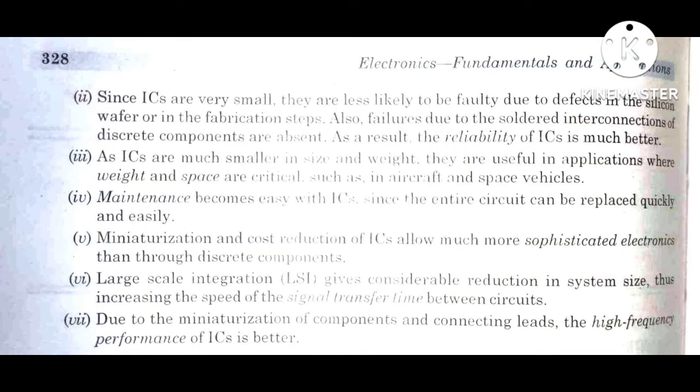Since ICs are very small, they are less likely to be faulty due to defects in the silicon wafer or in the fabrication steps only. Also, failures due to the soldered interconnections of discrete components are absent. As a result, the reliability of ICs is much better.